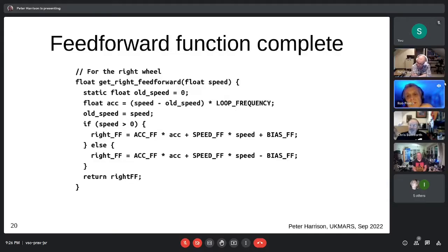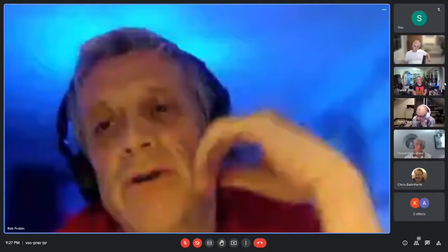I guess feed forward works because you can either anticipate the load or you've got a constant load. If you've got a load that you can't predict, then you've got to use feedback to control the system. But obviously, with most of these robots, the mass is fixed. We're running on a surface that's reasonably the same friction across it. It's reasonably level. So it's mostly a predictable problem.